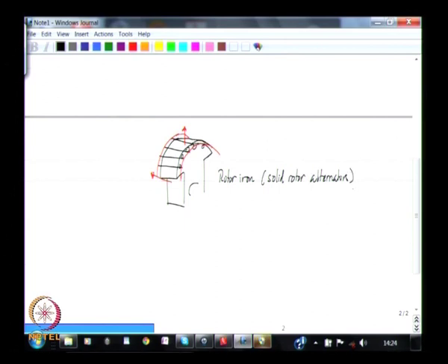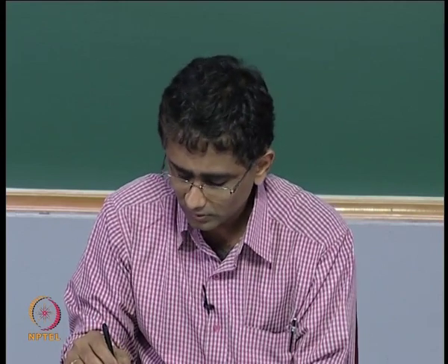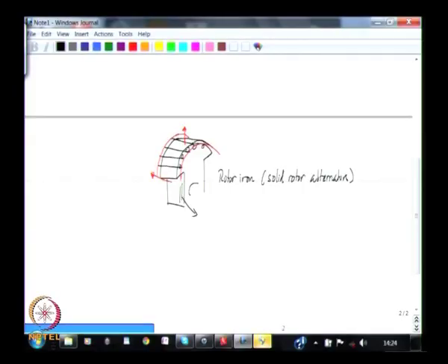under ordinary circumstances when the rotor is rotating at synchronism, since there is anyway no induced EMF, you need not have an arrangement on the rotor where the main field pole is being divided into rotor laminations, because in any case since the rotor is going to rotate at synchronous speed, there will be no eddy currents induced, no EMF is there, no eddy currents are there, and therefore it is not really necessary to have a laminated arrangement in the main physical rotor as such.